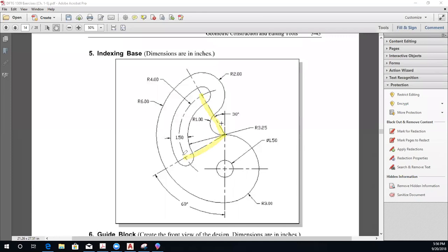So first, if we're using the polar coordinate system, it's going to ask us to identify the length of this line. We can see that these lines intersect this circle that has a radius of 4. You can see that the center point for this circle by the center line goes down right here. So this will be the center point, the top quadrant. So we'll make both of these lines 4 inches long. And then we can see that this is 30 degrees from the 90-degree angle.